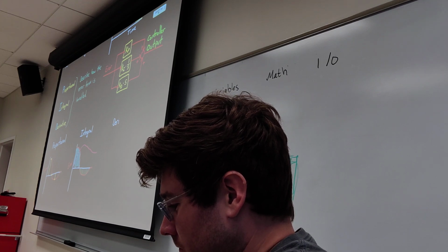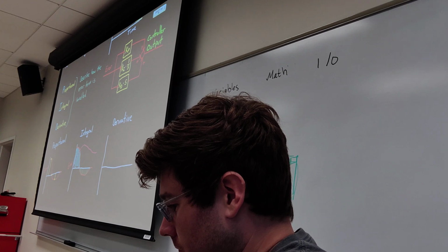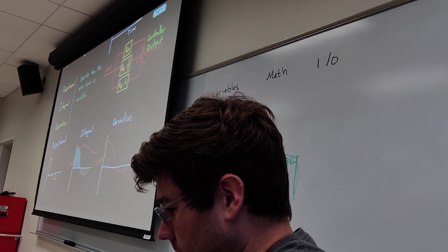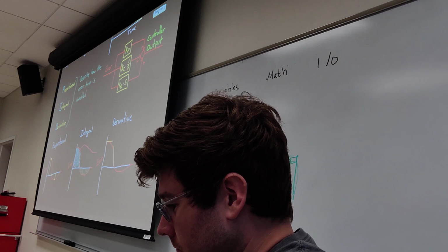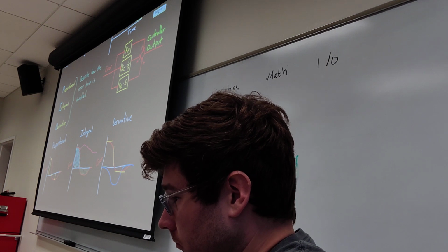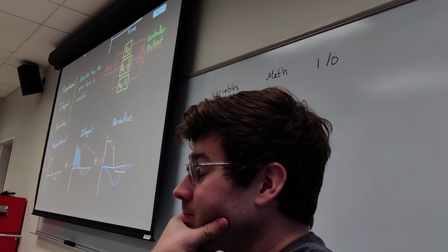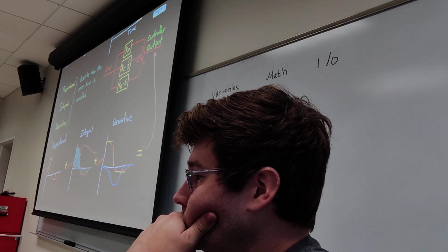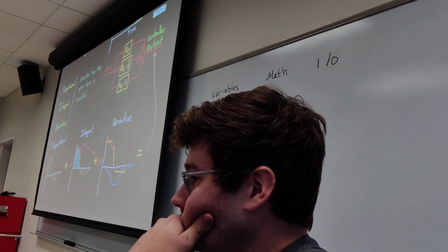Now, in the derivative path, it's the rate of change of the error that contributes to the output signal. When the change in error is moving relatively slowly, like it is at the beginning here, then the derivative path is small. And the faster the error changes, the larger the derivative path becomes. Now at this point, you can just sum up each of these three paths and you've got the output of a PID controller. But you don't always need all three paths.